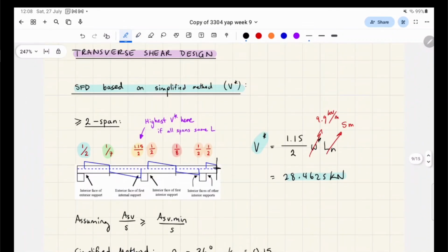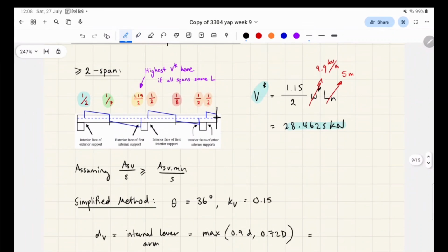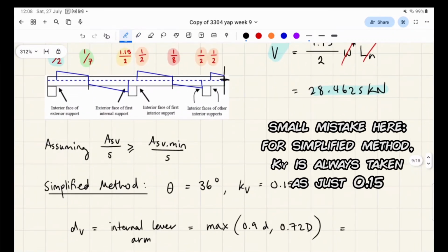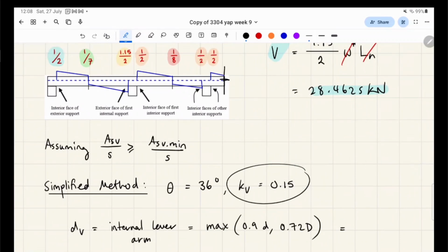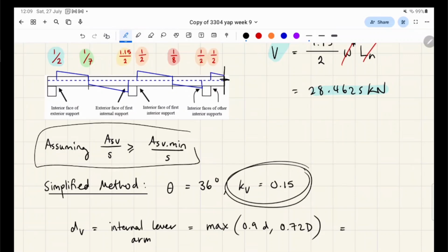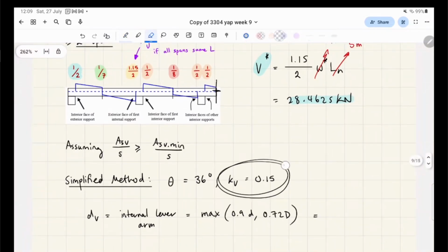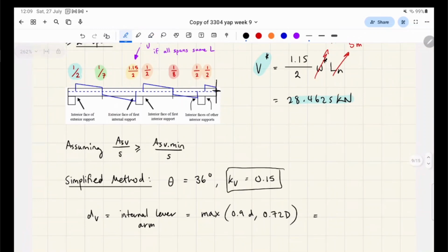All right. So with shear design, the value for kV depends on whether you have enough area of shear steel per spacing, greater than a threshold number that you can calculate. But we're just going to assume that it does satisfy the minimum steel requirement, in which case the formula is simply 0.15.